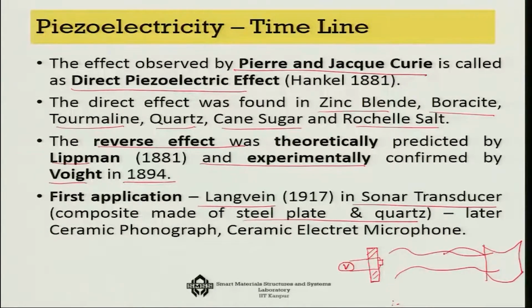So it is actually coming back, each of the waveforms, and some of them are hitting this piezoelectric element back. What will happen then? This piezoelectric effect, because of the change of the pressure wave, is going to generate a signal itself. So you can actually tap that and find out what this signal is, and that signal is going to tell you whether there is an enemy submarine or enemy ship or anything like that. Okay, so that was the first application that Langevin thought of, the piezoelectric effect.